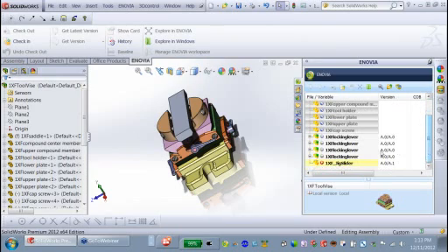Now, over to the side, we see that new part we just added in, and a red symbol next to it. What this indicates, as you can see by the highlight, is that the part is out of date. You're thinking, well, how can this happen since you're working from a central server? Well, for performance reasons, we keep a local cache of all of the parts sitting locally on the drive. We basically keep SolidWorks kind of dumb, per se, in that it's not looking across networks for files. It only looks in one local location, wherever my local C drive or my local drives are, to access the parts and assemblies I need to work with.